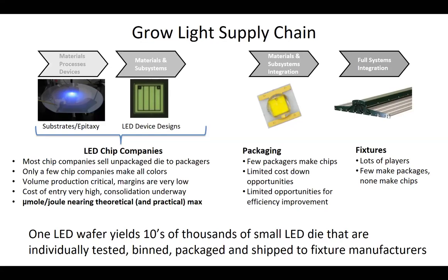My experience with solid state lighting, and I presume it transfers to fixtures as well, is that almost all the failures and limited lifetime issues that people have with fixtures happen not at the LED level, but at the fixture level. Drivers fail, solder joints fail. These are some of the things that fail. You can also get failure at the package level. Those silicone lenses can discolor. Somebody might have pushed on it. There may be some ESD event. The LED die itself is typically very, very reliable, and it will age gradually.